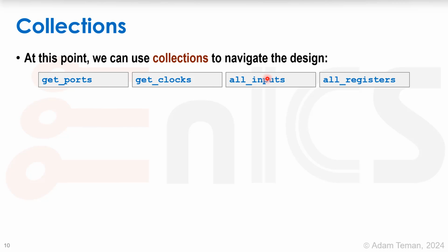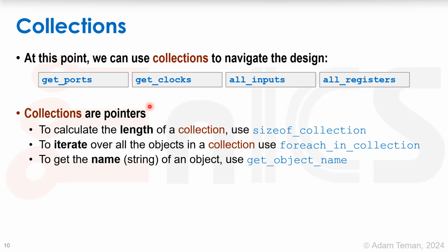However, these things all return what are called collections, and a collection is not a normal Tcl string. It's a special type of database unit that has all kinds of properties and so forth. It actually returns a pointer or a handler, just some sort of a number in hexa that is whatever the collection is. So when we want to do things on it, we have to use special commands.